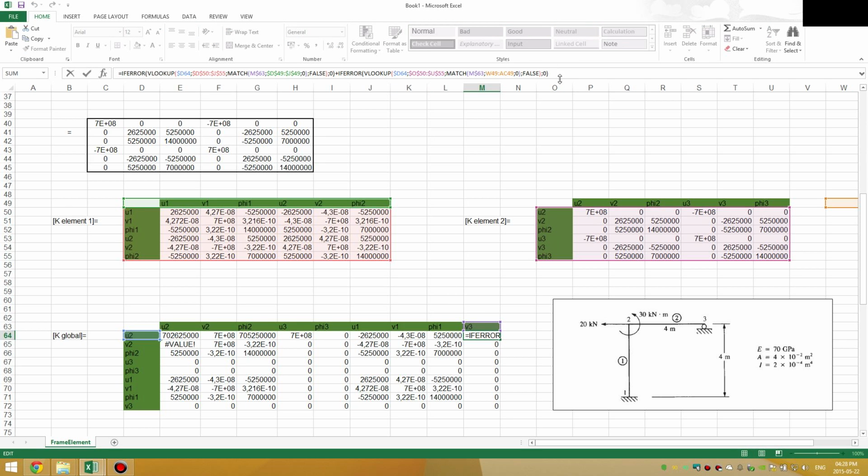Let's just have a look. You see that thing is not fixed. Okay, let's just correct that. I forgot to fix that column. So press F4, F4. See what happens when you don't fix everything. You get zeros everywhere, and this should indicate that you did something wrong.